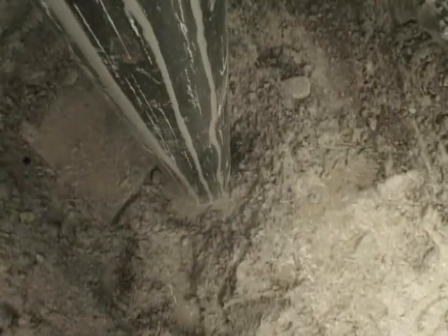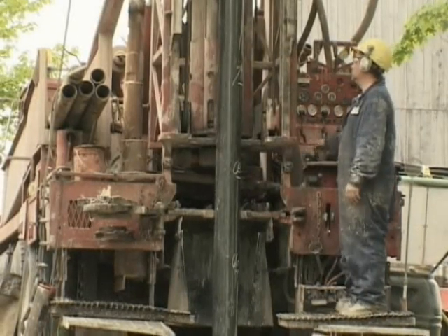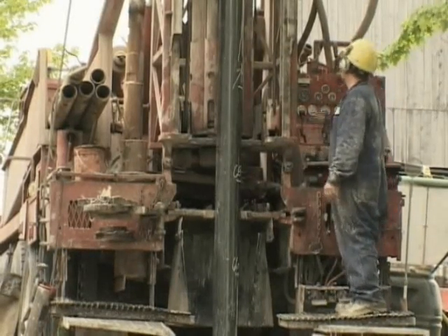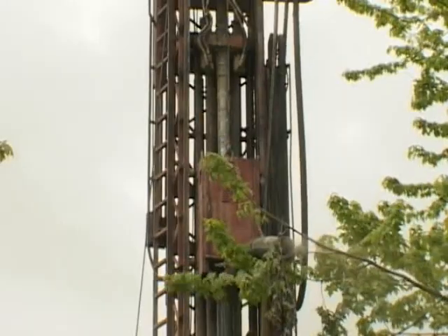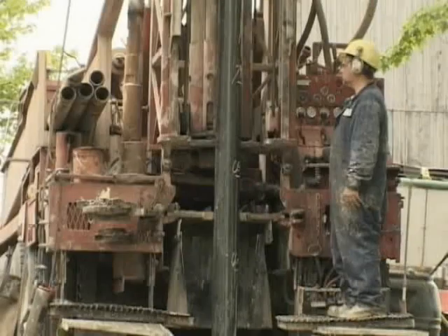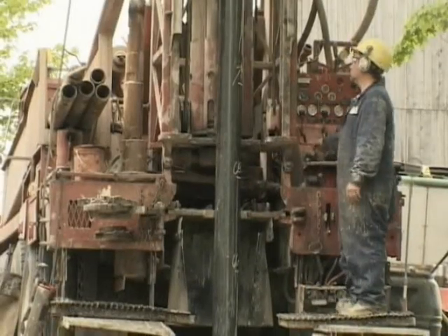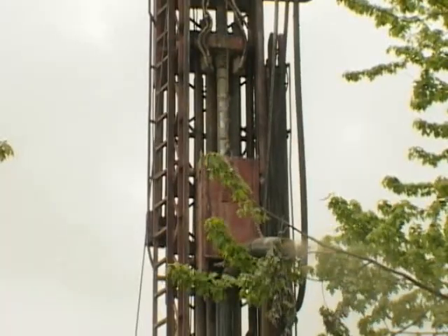In this particular well, the grout was installed between the oversized working casing and the finished casing, then enabling the working casing to be removed and drilling to continue. The technicians drilled approximately 4 to 5 feet ahead of the casing, and shown now is the casing driver rapidly advancing the casing. Drilling of the borehole then continues in the stabilized hole.